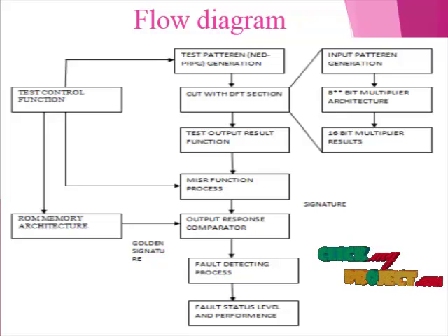The advantages of BIST include the capability of performing at-speed testing, very high fault coverage, elimination of test generation effort, and less reliance on expensive external testing equipment. The BIST techniques are classified into offline and online. Circuit under test is the portion of the circuit tested in BIST mode. It can be sequential, combinational, or a memory. Its primary inputs and primary outputs delimit it.